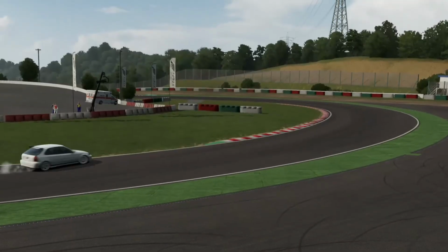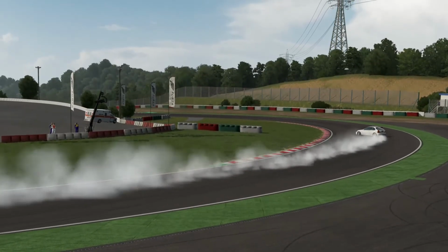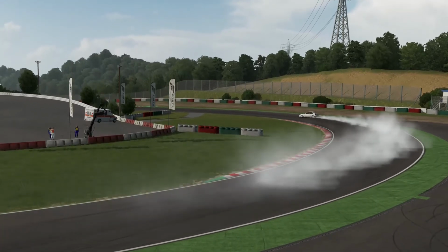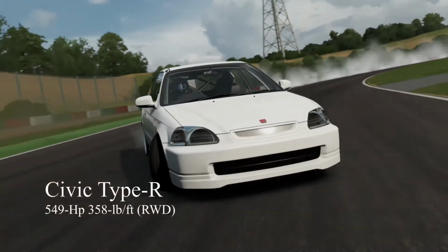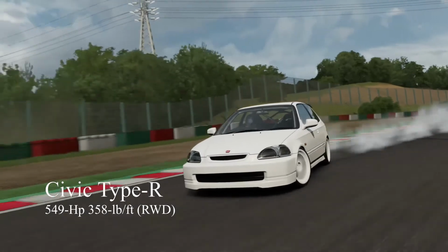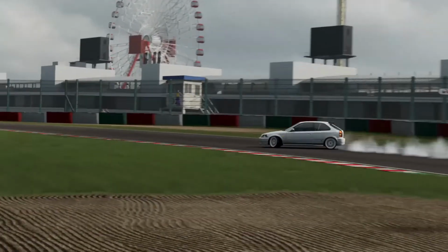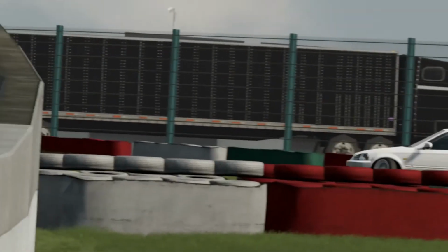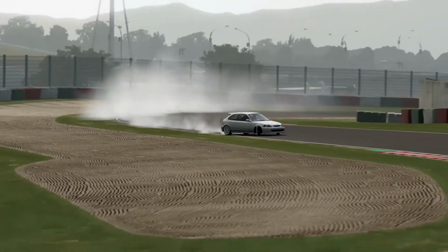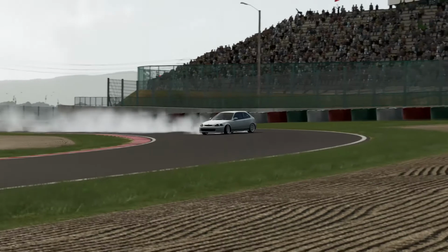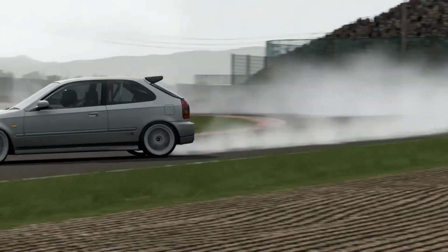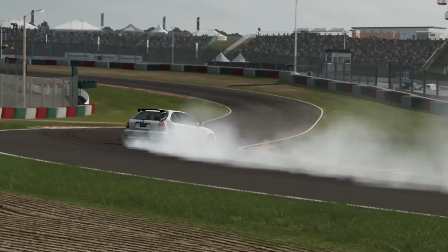When a car is drifting, the angle at which the vehicle travels is not forward-facing. Because of that angle, the amount of airflow that passes through your cooling components is significantly reduced. For this application, you want to have a fan override switch and/or relocate your cooling components so they experience more airflow during and after operation. Remember, always do a cooldown lap.